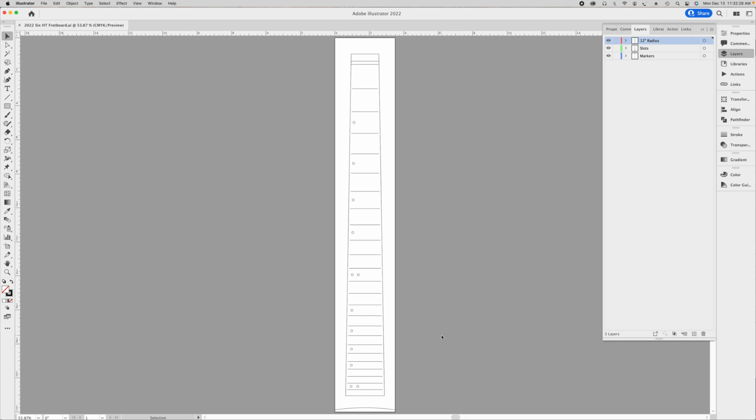So, as I said before, there will be 4 different carving operations, and that's because I'm using 4 different bits to cut the fretboard. So I'm going to have one operation for drilling the fret marker dots as well as this slot up at the top where the nut will be installed into the fretboard. Then I will have another carving operation to cut the fret slots.